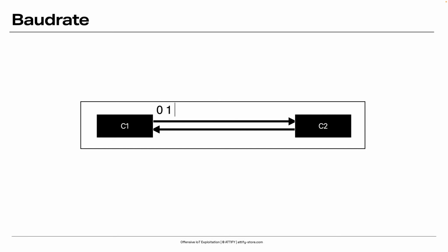So that's about UART. And in order to interact with UART, we also need something called baud rate, which is the speed at which the data communicates or the data transmission happens. There are some standard baud rates like 1200, 19200, 57600, and 115200. This is simply a standard value agreed upon by both the chips so that the data exchange happens smoothly and fluently.